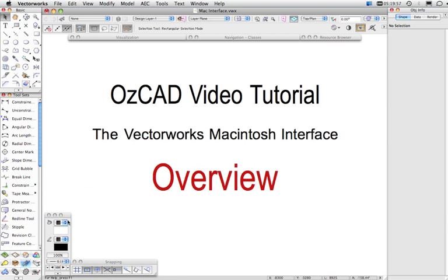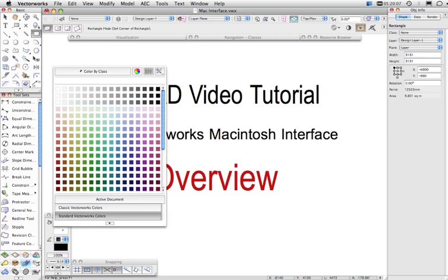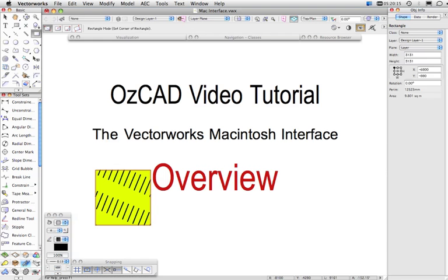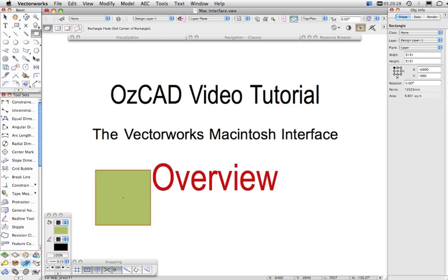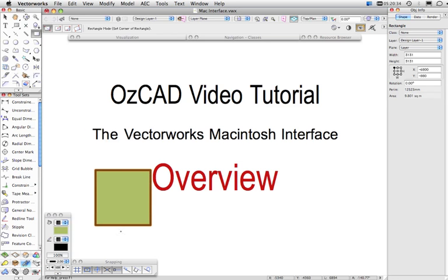And then we have the attributes palette, and this is the palette where you can control things like the fill color, the style of fill, no fill, solid fill, pattern fill, hatch, tile fill, gradients, image fills, and so on. You're also able to set the line weight here. If I choose line weight, I can bump up the line weight of the object.